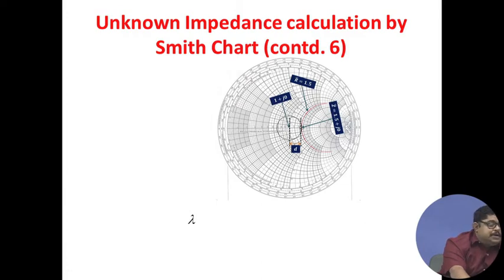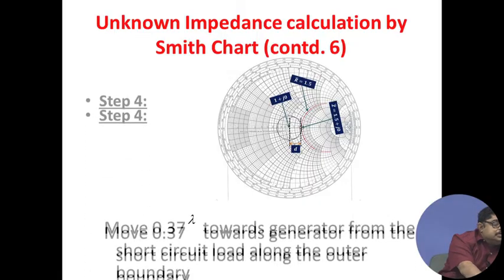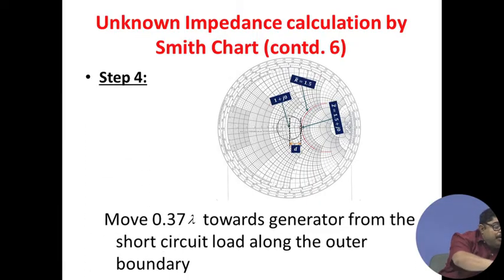So, it is at the left end. You plot the Smith chart, then from the short circuit, we have seen that we will have to move 1.48 centimeter, which happens to be at 7.5 gigahertz. So, lambda will be 30 by 7.5 centimeter.